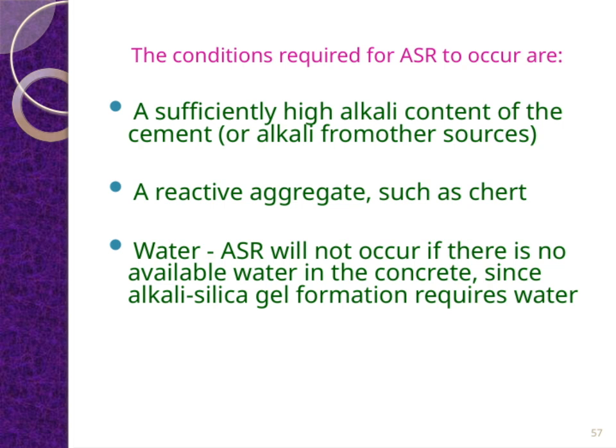Remember, ASR won't happen if there's no available water in the concrete, because the formation of the alkali silica gel requires water to occur. So the main conditions for ASR to take place are, first, enough alkali in the system, second, a reactive aggregate like chert, and third, the presence of water. Without all these elements, the reaction simply can't proceed. Understanding these points helps us better design durable concrete mixes and prevent future deterioration.